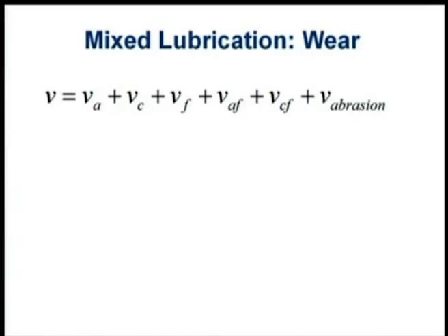In dry conditions there is a possibility of strong abrasion and strong adhesion, but when we talk about wear in lubricated conditions, there is a possibility of some sort of adhesion where the asperities are still in contact, and some sort of corrosion, maybe the lubricant is corroding the surface or some process fluid getting mixed with the lubricant causing the failure.